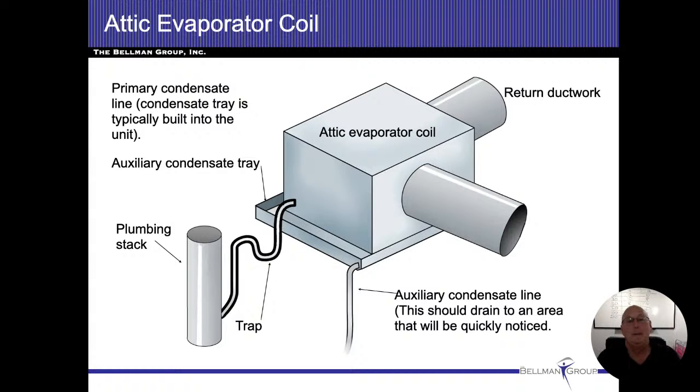All right. Now, if we're on the first floor or in an attic install, we need to have a secondary means to protect against any sort of overflows or clogs that come into play. So if we're in an attic or anything other than a basement concrete floor, let's put it that way, if I have structure underneath us, we need to have some sort of protection. Even with a crawl space, you have to do that too.